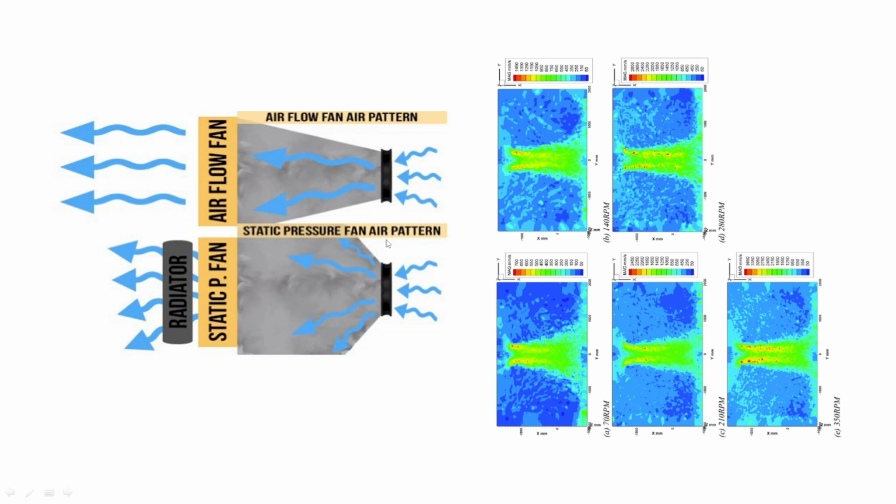Now, if you are looking at radiators and AIOs, if your radiator is on this side, where my mouse is, so the fan is in a pull configuration, the airflow coming out of the fan will be the same as if it was an open airflow type. Just the amount of air might be different, meaning its air velocity, because it's having to suck air through another object, through your radiator. But the airflow pattern will be similar or identical. So you actually do want a good fan with constant airflow if you're going to use it in that configuration, so that the air travels through your case to cool, sort of arbitrarily, every other component in there.